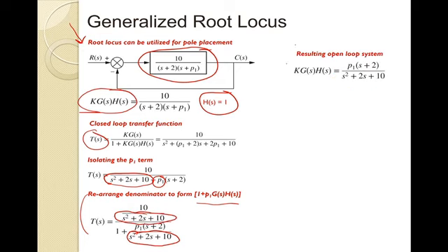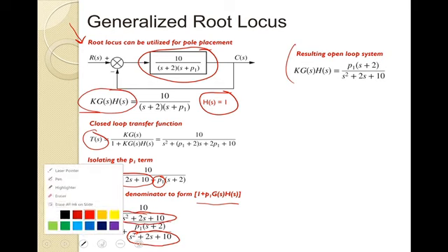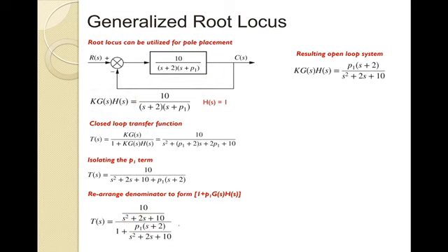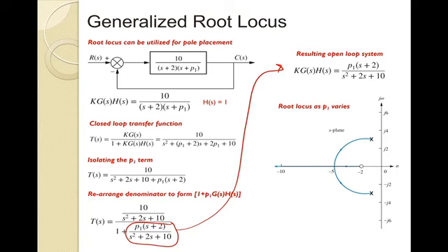And then so the resulting open loop characteristic from that system is exactly, let's get rid of some ink here. Okay, it's this term right here. Okay, this term right here is our resulting open loop gain. Okay, the equivalent, what we previously called KGH. Okay, so we have that characteristic right there. And now what we can do is instead of varying K like we've done previously, we have P1, that pole, as a knob we can turn to see what happens.